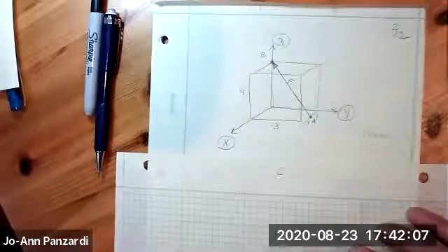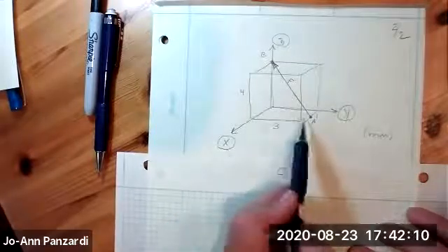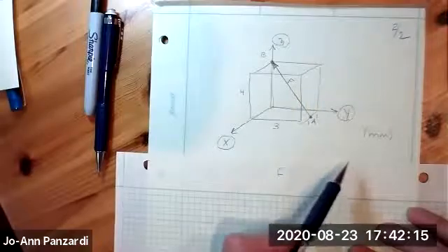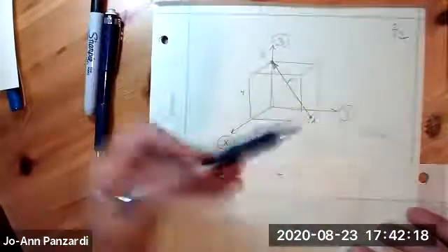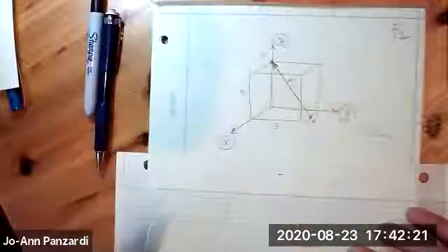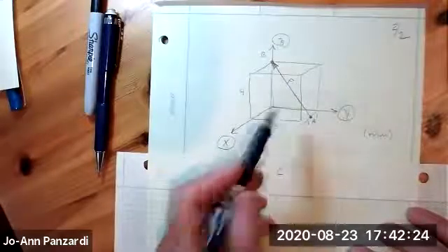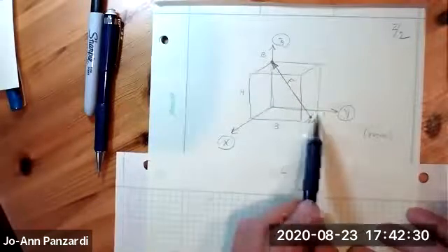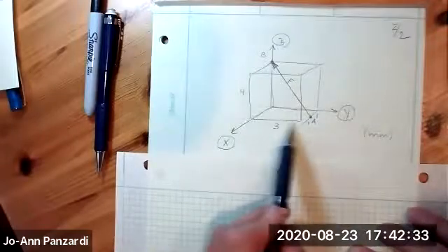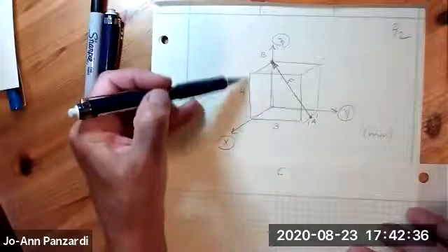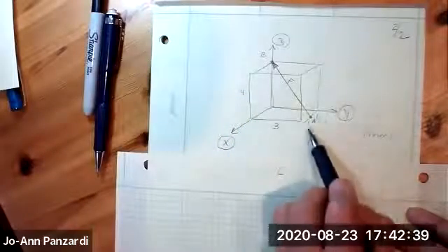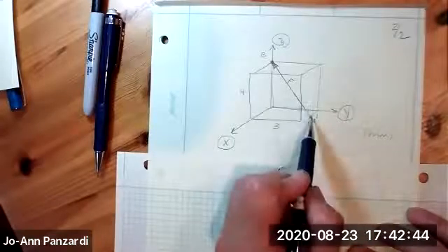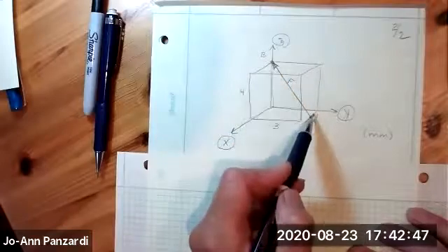Does everybody see that? The one that might be a little challenging is the X. Just realize that here's the front face of the box. A is the middle plane of the box, and B is in the back. It's going from A, the middle plane, to B. It's going in the negative X. So now let's figure out what is the distance it's going. Well, going from A to B, I've given you all these dimensions, right? So 3 represents the total width of the box, 4 represents the total height of the box, and the total depth of the box is 2, but A is starting halfway back. So if we're going from A to B, we're going -1 in the X.